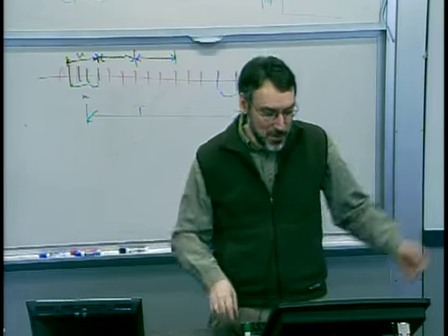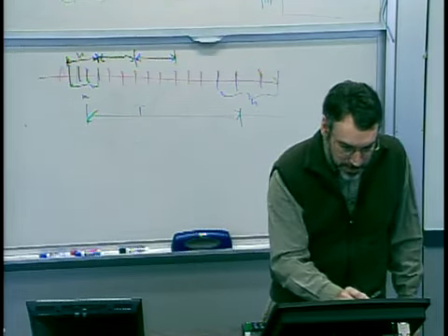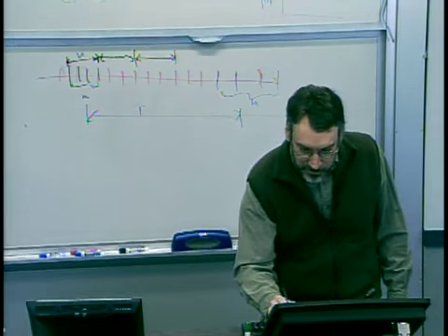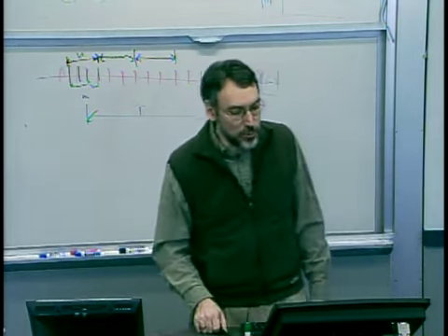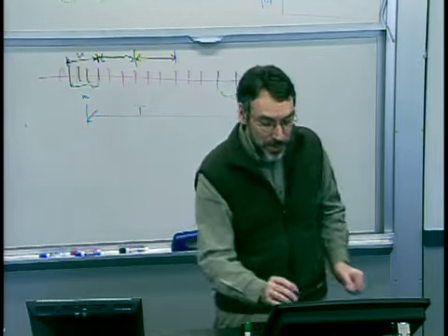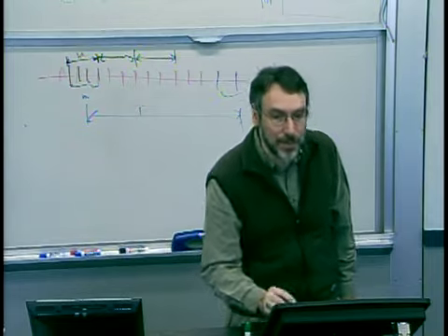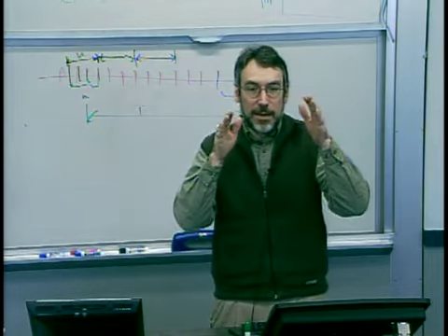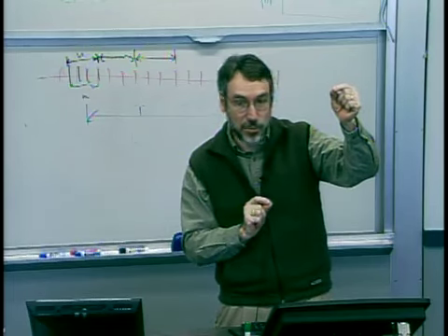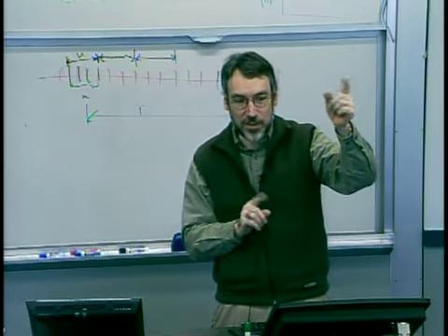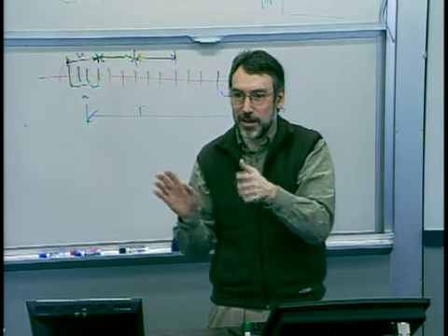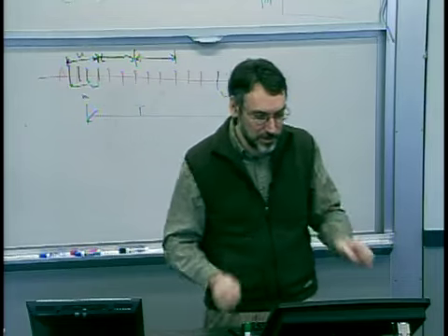So you don't know. It may well be that I've got really tight spec limits. My parts really need to operate down in here. By the way, you also have to be careful because if these are based on N samples, the sample distribution is tighter than the underlying process distribution. So if you see spec limits also on your control chart, that's kind of a warning, because usually a control chart is based on sampling, right?